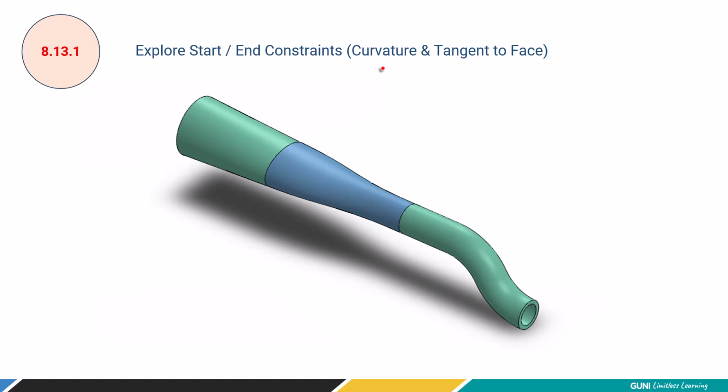Before we continue to explore other options like curvature, let's understand the difference between tangent to face and curvature. Let's say I have a curve like this. If I add another line in this direction, I can say there is a tangency relationship. But for the same thing, if I continue this curvature in this direction, then I would say it is called curvature continuous.